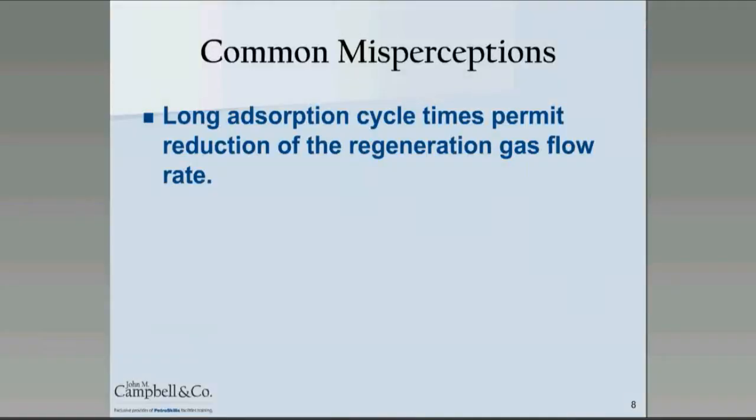Let's shift subjects and go into some common misperceptions that we find about adsorption times and pressure drops. One misperception is long adsorption cycle times will permit reduction of the regeneration gas flow rate. Now, this is true. If you have long adsorption cycle times, you can reduce the regeneration gas flow rate because you have more time to complete the regeneration. But there's a limit to how low you can go.